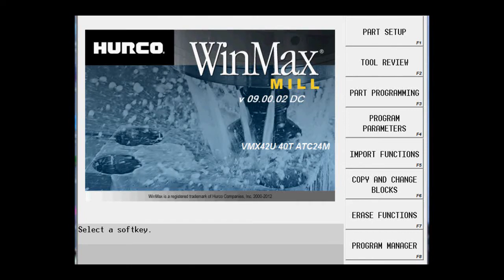The principles for the Intro-28 print are just like the previous Intro-27 print we just did. We're going to drill one hole in the farmost left print in the bottom left corner. We're then going to pattern that hole into a grid of 5 by 5, or 25 holes. Then we're going to take that group of blocks that make up that grid pattern and pattern it in 4 locations total.